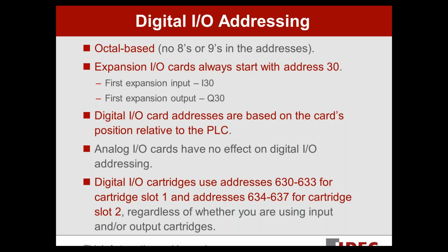Now, if I physically swap their positions, in other words, I take the card that's in position 2 and move it to position 1, take the card that was in position 1 and move it to position 2, that will change the addresses of those cards because it's based on the card's position relative to the PLC. We'll look at this in the software. It will make more sense to you.